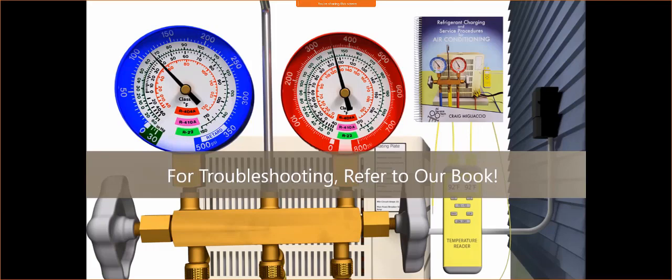If our evaporator coil is 32 degrees, we are no longer removing water and humidity, dehumidifying the space, but we're now turning everything into ice. 32 degrees is the temperature water freezes, so our air conditioning system now has turned into an ice maker.